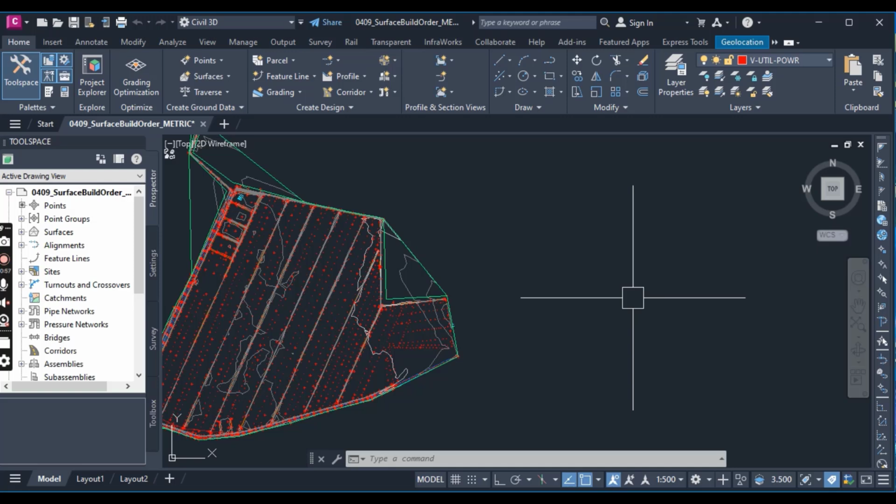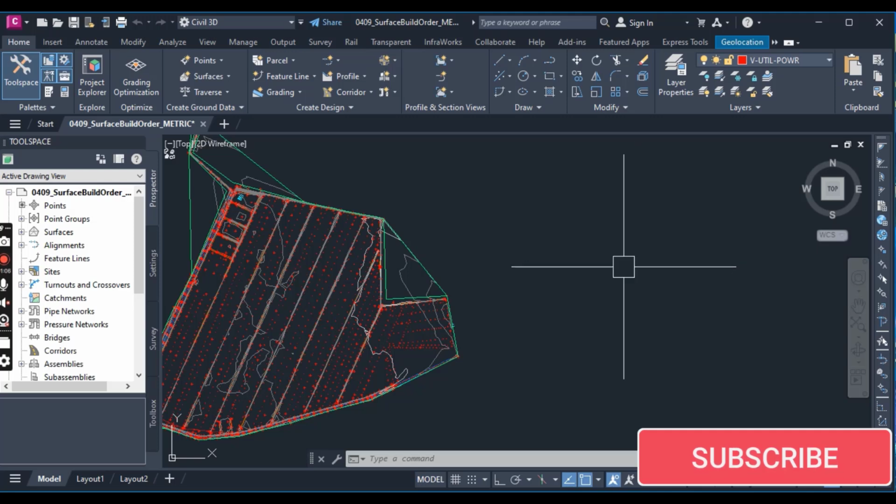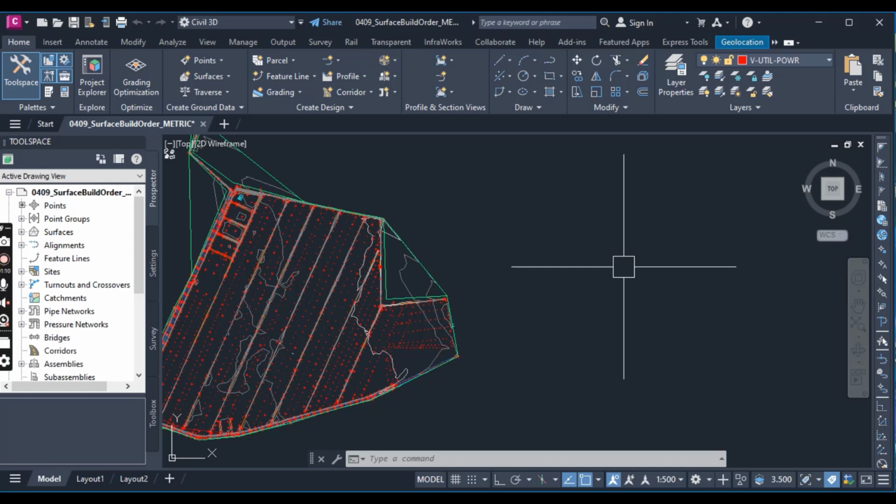The survey data is compiled into a separate surface as described earlier and then pasted into a surface containing the GIS contours. Then boundaries will be added. So if we are going to create a proposed surface, it will usually be composed in this order. First we will paste roadways and pond surfaces, then proposed breaklines and hand-drawn contours, and then boundaries at the end.